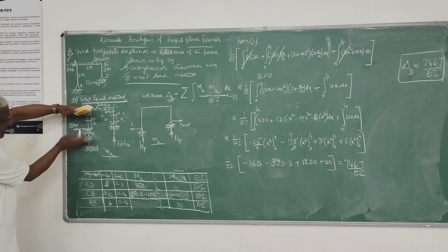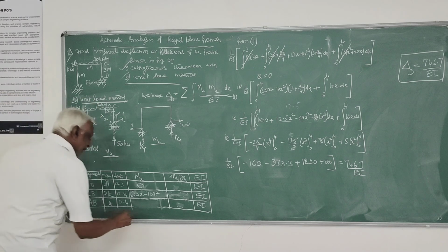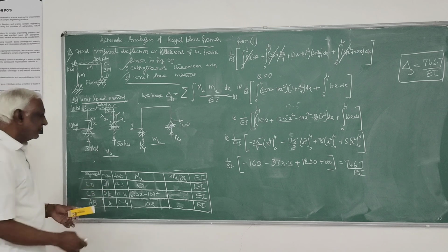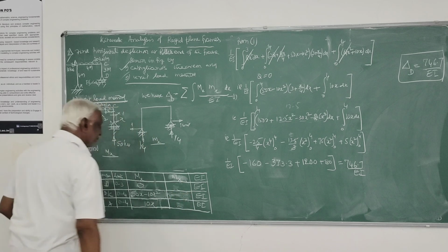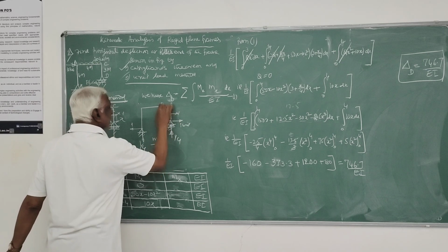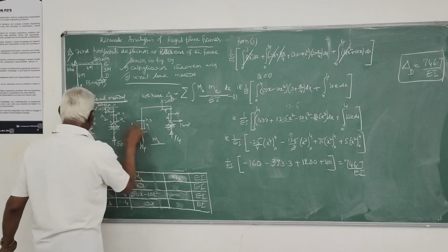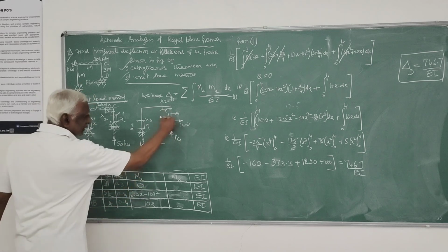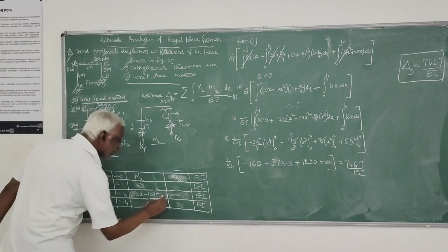Here, I will take this side. This will not give any moment. 10x, this 10x sagging inside. So it is 10x. That's all. Then small mx. Instead of delta mx by delta q, it will be small mx. Here, this is the first section. Distance is here. Second section, distance is here. Third section, distance is here. Same as whatever you have taken. This section moment, this will not give any moment. This will be 1 into x, again sagging towards inside. Sagging, x, so it is positive.